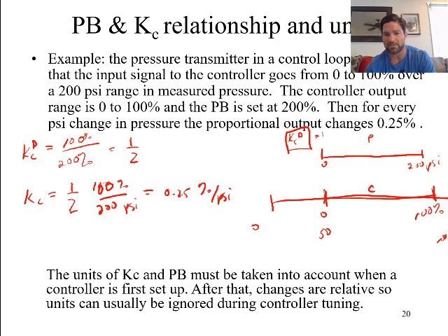So essentially we're looking at, here would be 50%, that would be divided by 4. So this right here would be 25, 50, 75, right? So we're only using on the controller 50% of the controller for the 200 psi sensor range, which means that in terms of our actuator, we're only really using half of the actuator movement for the controller.